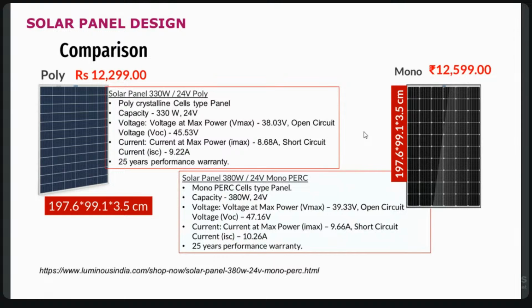This solar panel will be installed for the long term, more than 10 years or 20 years, because that much warranty will be provided by the manufacturer. So they will go for the higher amount only, but they need higher efficiency and low maintenance cost in coming days. So generally they go for mono. But in some domestic applications we use poly, which is less amount. In domestic applications, generally they go only for less money, but in industrial applications, they go for the higher amount of money.